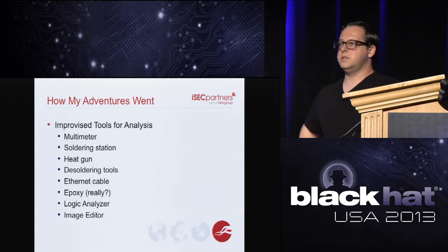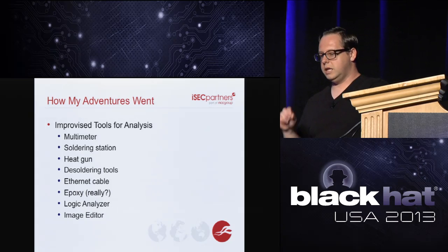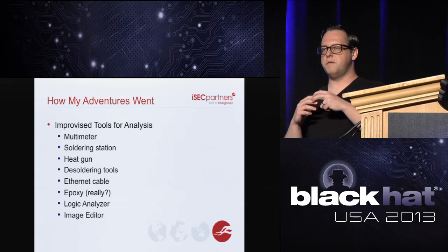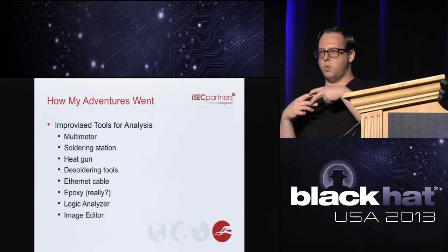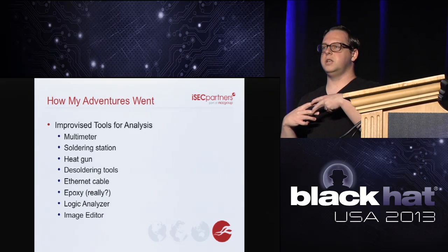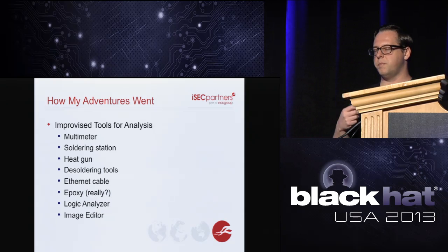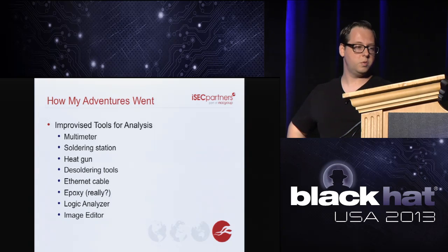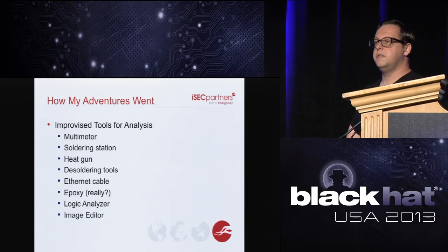The other thing it can do is, if you have really small leads and you want to get some wires on there, if you're just right and you put enough pressure on there, you can push the wires on and glue them together. So you can actually glue the wires with epoxy directly to the leads and do some sniffing as well. Logic analyzer, this is crucial for figuring out what's going on on the board, what protocols are being used, what buses are sending data when.